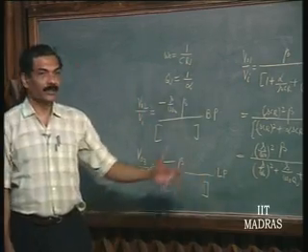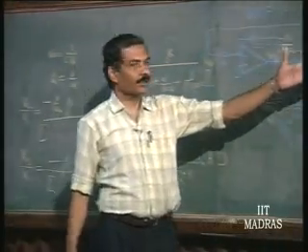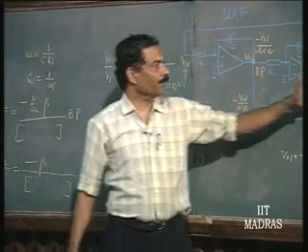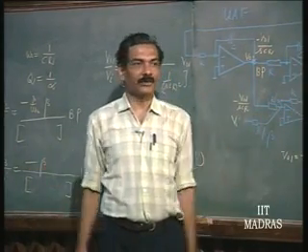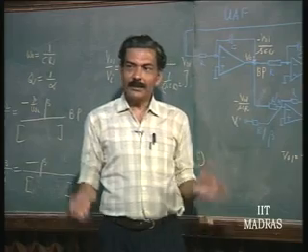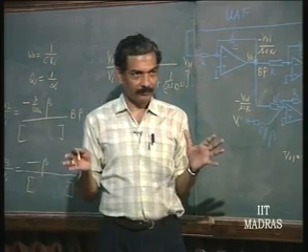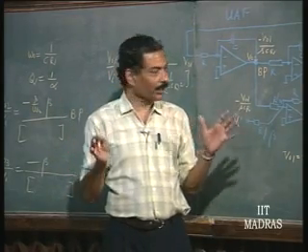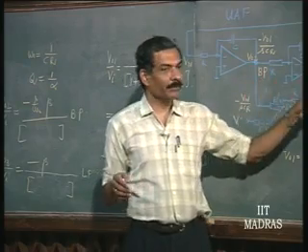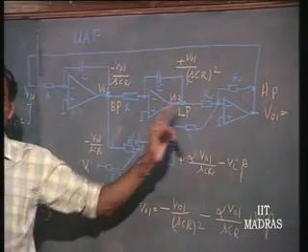That is why there is some universal nature about it, because band pass, high pass, low pass, if you can add or subtract suitably, you can get any second order system. Any second order system block can be got by adding suitably or subtracting suitably these outputs.